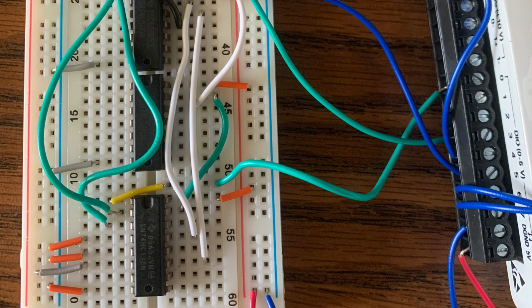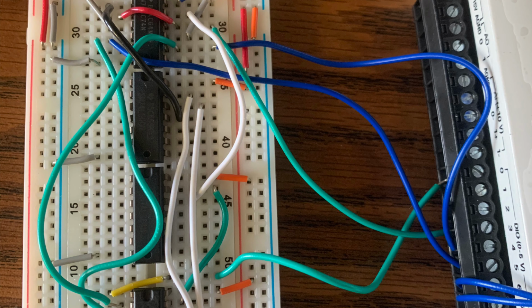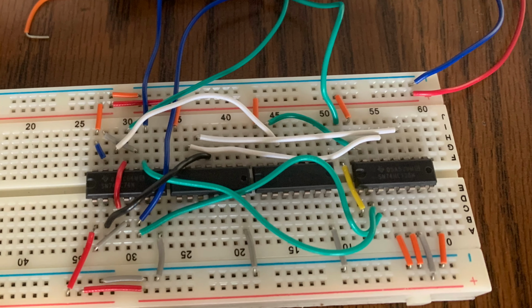Next, we connect the logic by taking output Y1 from the decoder through the NOT gate, the bottom IC, before attaching it to the input on the right side of the flip-flop, the green and white wires. You can also see the 2 white wires from outputs Y2 and Y4 that go through the NAND gate. Now we have our entire flip-flop wired and can test. We'll test as we fill in the state table, and you can see our results in the following clip.